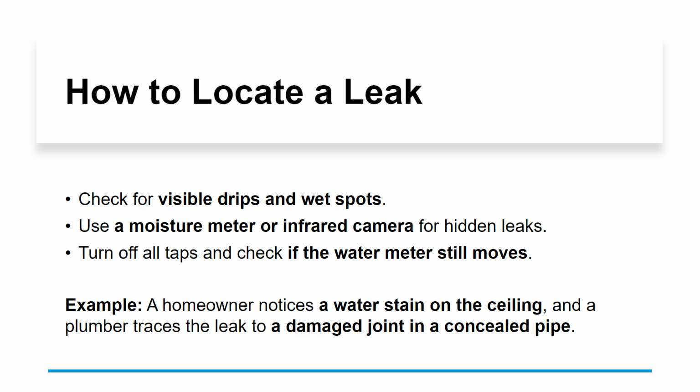Step 4. Use leak detection tools. Spray soapy water on joints and fittings. Bubbles will show air or gas leaks. For underground leaks, pros use acoustic sensors, pressure testing, or infrared scanners.